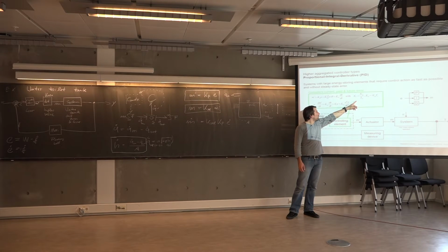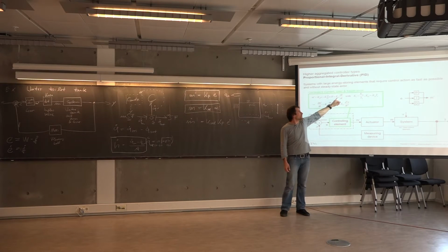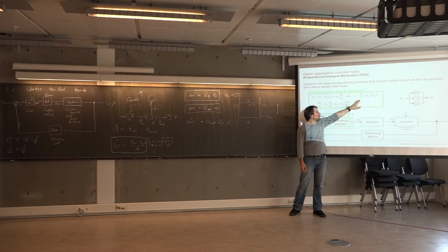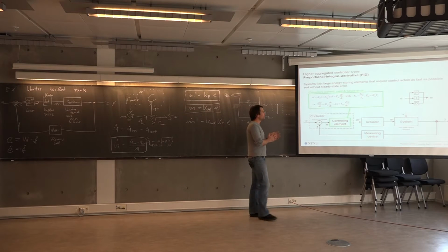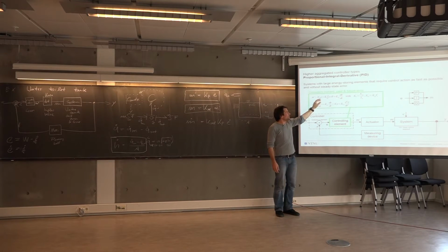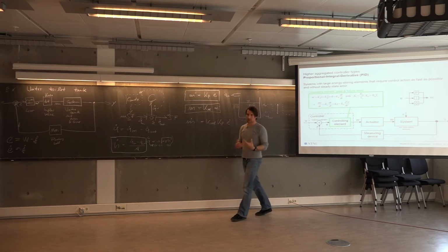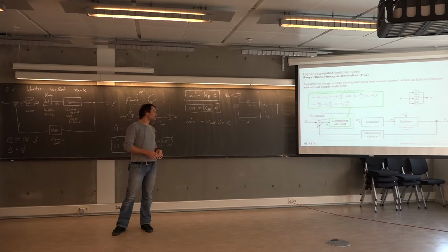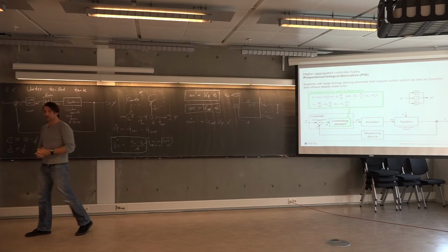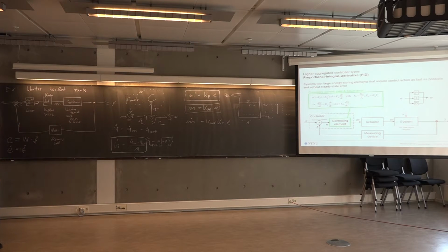You can basically exchange these Ki and Kd factors here using these expressions. The benefit of this is that this Kp then is valid for the whole equation, but it's just another way of writing it. But you may see these two different concepts in the literature, so you need to pay attention to what form of the equation you are looking at. If you take some example or some numerical values from somewhere, this is something to consider.